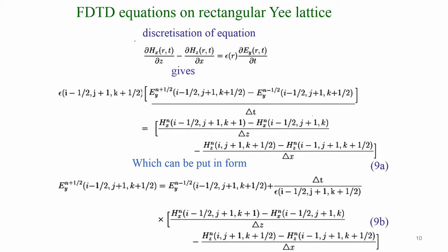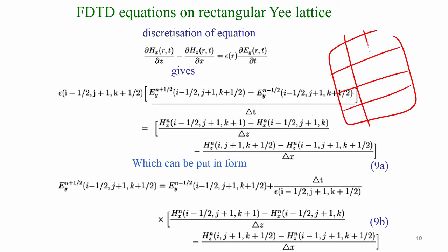Basically, this FDTD method discretizes the field in both space as well as time coordinates using difference techniques like central differences and so on. We need to divide the entire area of operation into a grid of very fine grid points, and at each point you define the field at the middle or at the end at some particular point and express it in terms of the neighboring points.